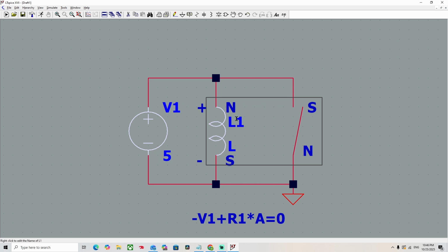Again, this is specifically for DC relays. If you were to put the current the other way, remember that the North Pole and South Pole switch, and south repels south and north repels north, so it would not close. So that's why DC relays require some amount of polarization.